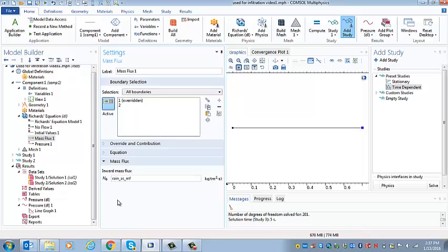So that would be what we would want to do if the rainfall coming into the lysimeter was uniform over the entire analysis. Well, if the analysis only lasted for 1 hour, that would be okay. But we'll want to do an analysis for, say, a day to look at what happens when we have the rainfall into the lysimeter, and then after the rainfall that water will redistribute. So in order to do that, we're going to have this boundary condition last for 1 hour as rainfall, this flux, and then the flux at the top will go to 0.